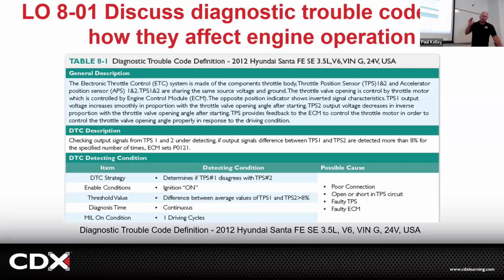So like I was saying, when you push the accelerator pedal, an accelerator pedal position sensor reads it. And then it gives it to the PCM as an input. So if you push it halfway, what would that be in percentage? 50. But technically, your sensor doesn't read in percentage, right? Your sensor reads in voltage. So they're going to determine what voltage equals 50%, right?